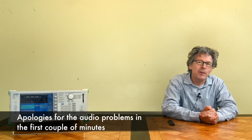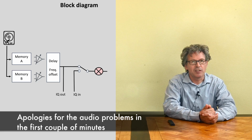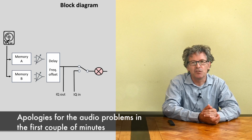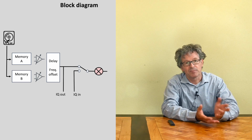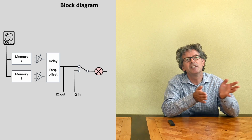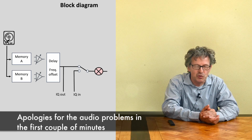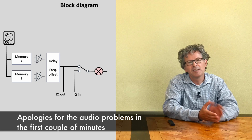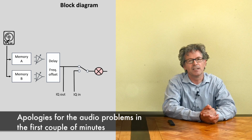And let's remind ourselves again quickly of the block diagram of the device. This is a sample player, you could say. So we got a sample coming up from a hard disk, which is loaded into memory. That's memory A and memory B. Playing from these memories can happen at the same time, or you just play one of them. You can change the amplitude of it. You can change the relative delay. You can do a frequency offset of them. They're going to be combined, and then they're basically sent to the RF generator in the device. And you can also take out the IQ signal or connect other IQ signals into the RF modulator.